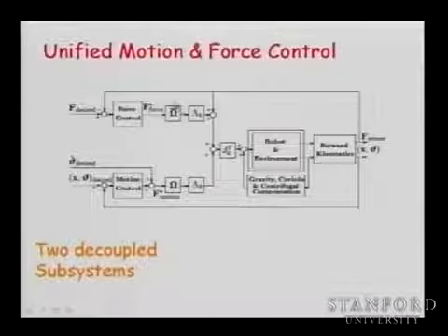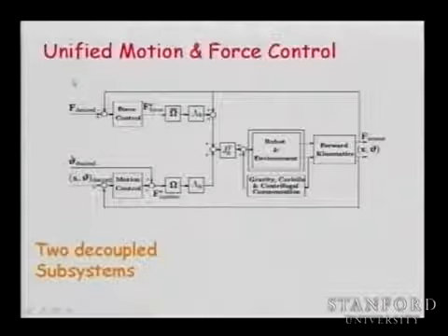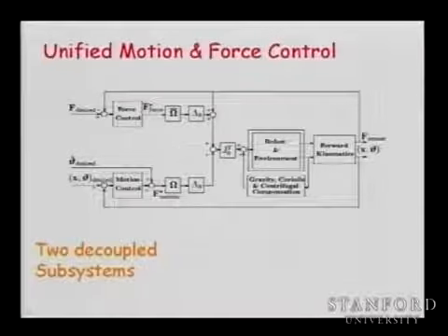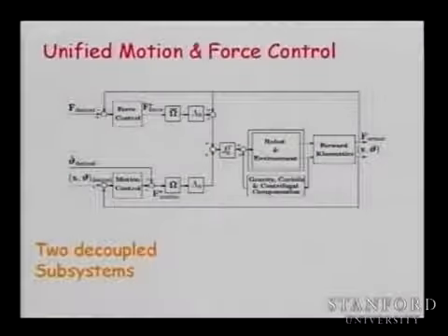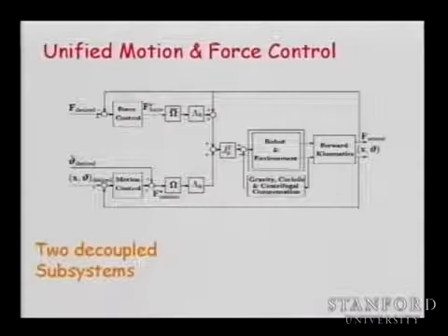Now what we are doing, we are projecting those controls in their spaces, and we are doing unified control of motion and forces. And because we are controlling everything in the task space, so we have F motion, F forces, we just add them together. We have a total force that we transform into a torque through Jacobian transpose. And that is what is nice now. You unify all the characteristics. So you can see some lambdas and some other things.